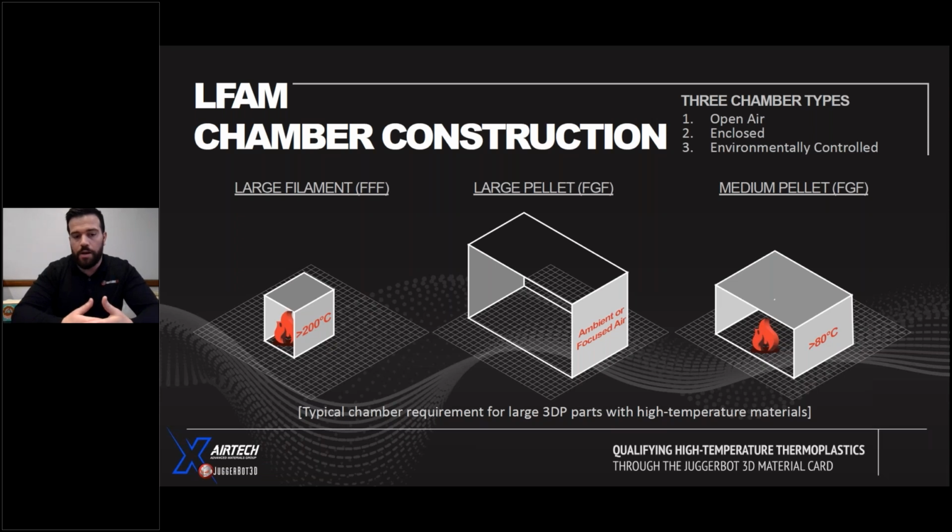But the third option is environmentally controlled chambers, and this is different than enclosures in the fact that it's constructed in a way where the operator can actually manipulate what's happening in the process by removing or mitigating humidity and increasing the temperature of the build chamber specifically.